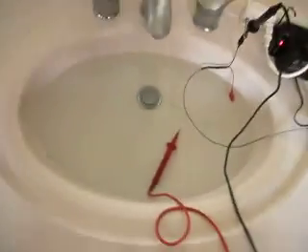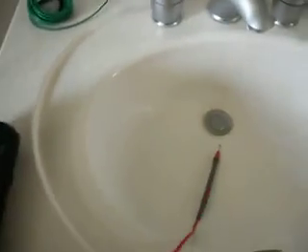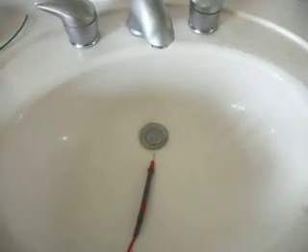So obviously I'm not happy that my water has a voltage on it. My remedy for this problem is over here. I've actually put grounding clamps onto my water system to take the voltage off, and this cable currently runs to the grounding connection on the wall outlet. So let's see what happens when we fill the basin.